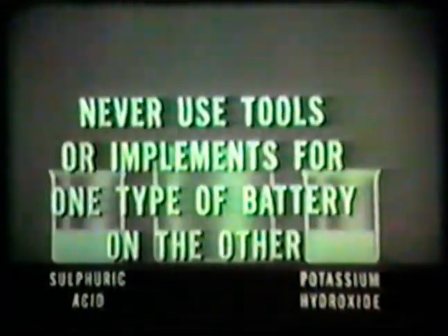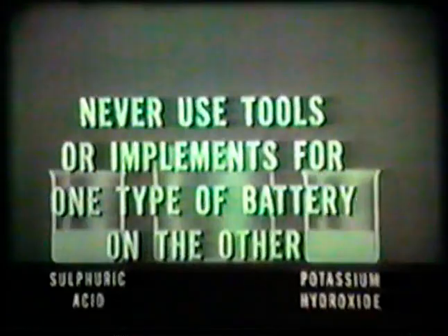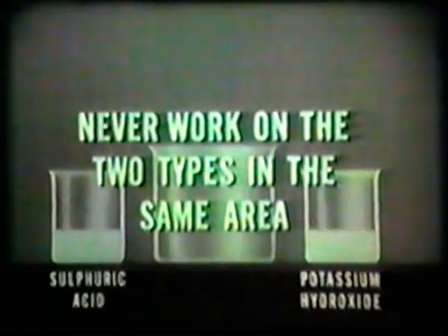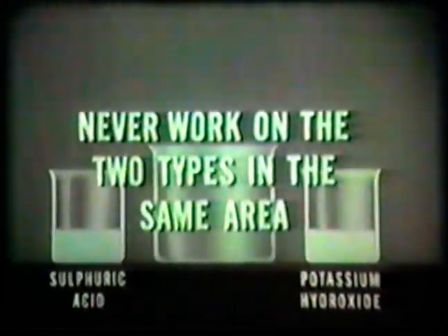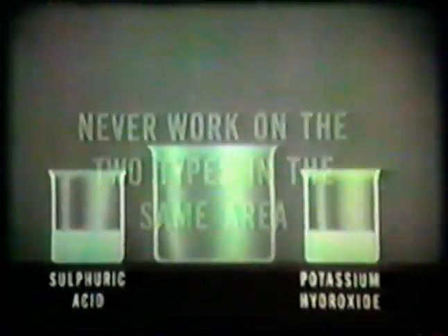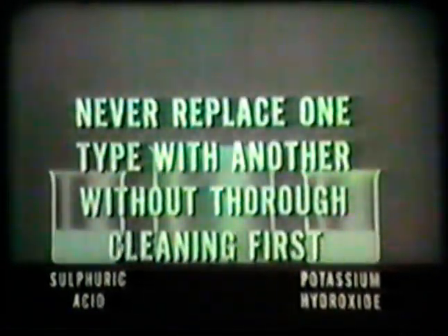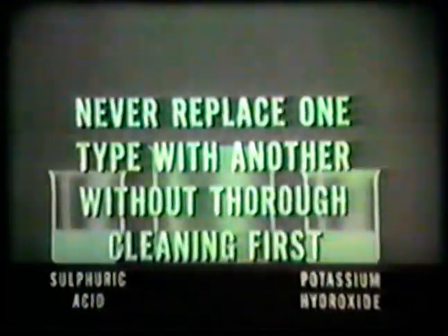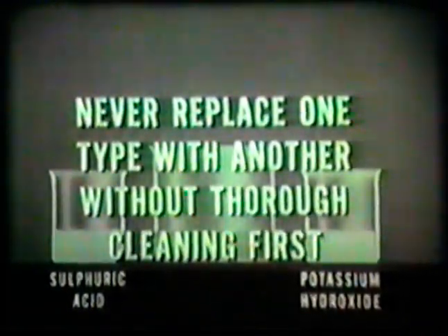Never use tools or implements for one type of battery on the other. Never work on the two types in the same area. Never replace one type with another without thorough cleaning first. This means cleaning all the components.